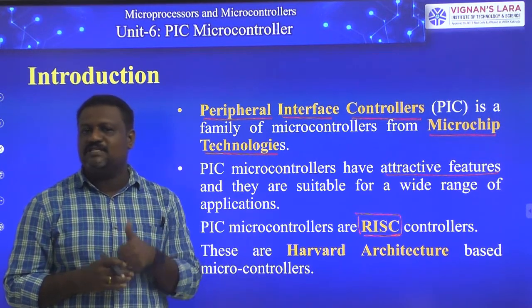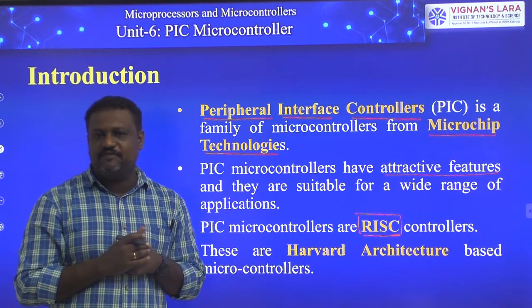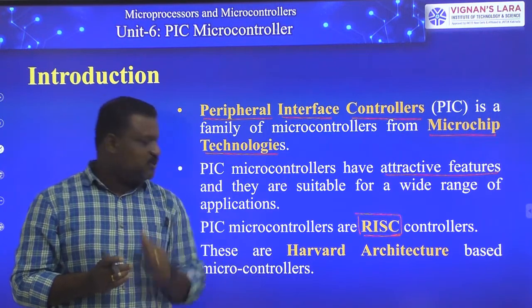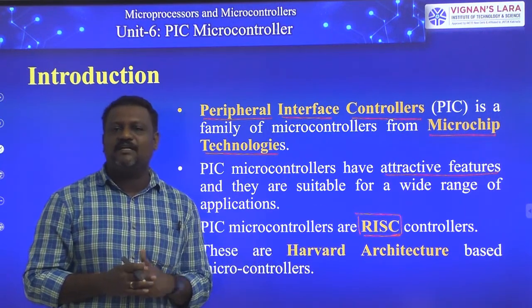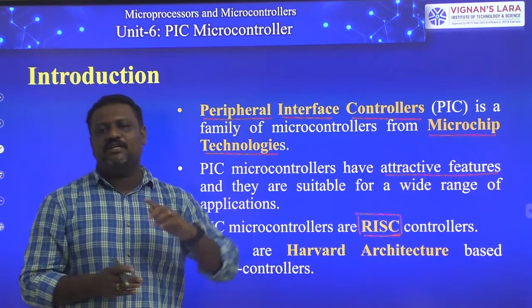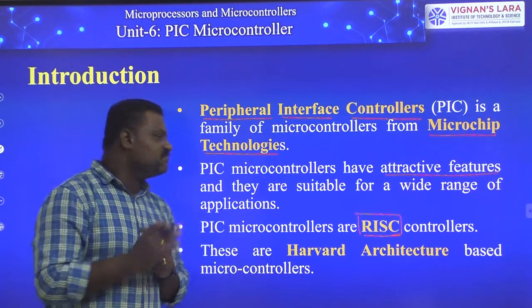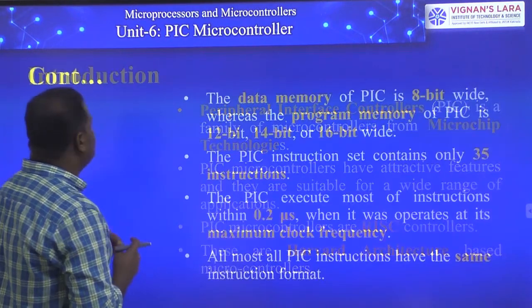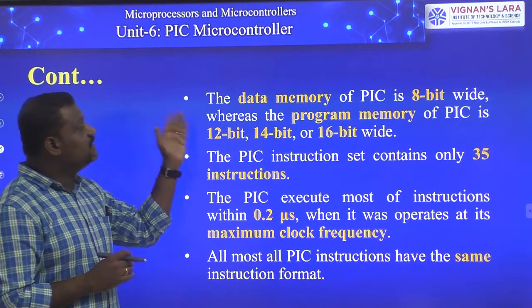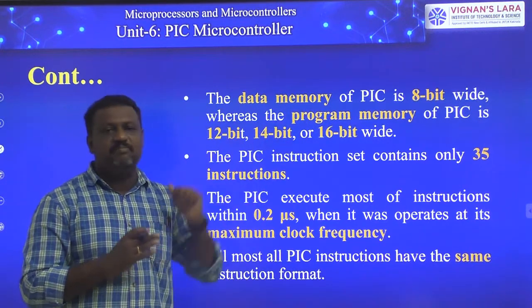One, it supports RISC, due to which the speed of operation of your system increases, and number two, it supports Harvard architecture, so that it also increases the speed of operation. So these are the two important features. And next, the data memory of PIC is 8-bit wide.